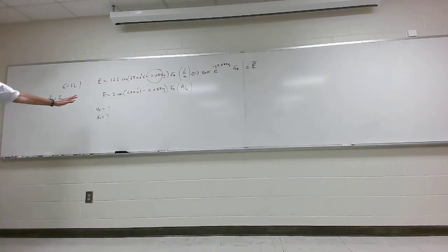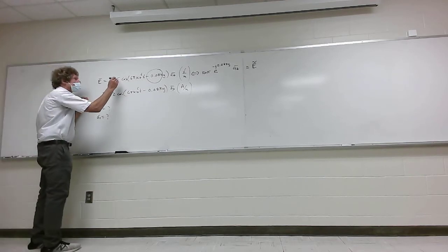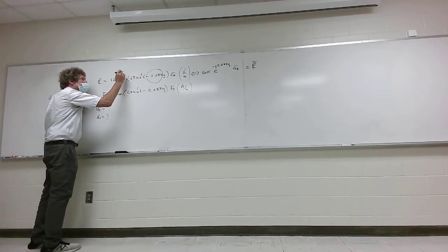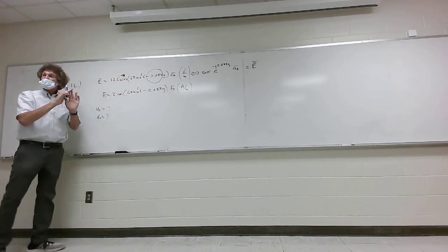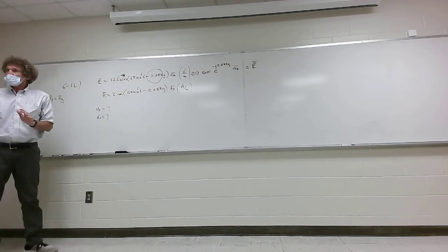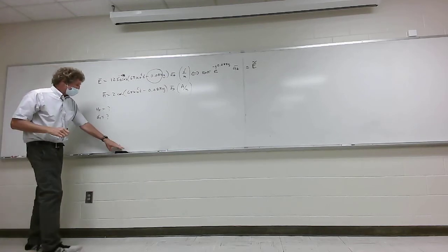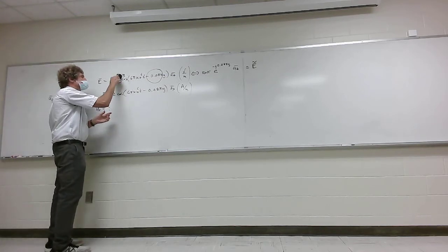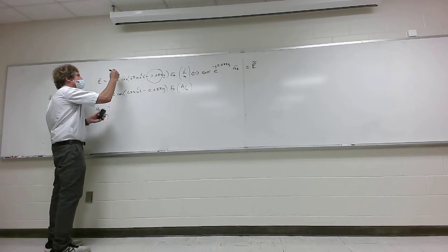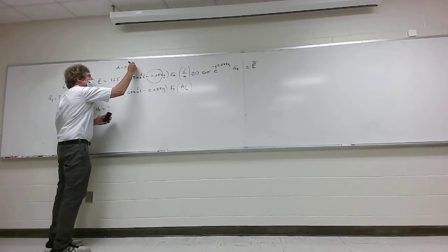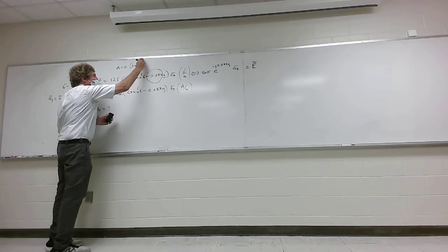All right, now he wants these things. You correctly identified the direction of propagation as positive AY. Now the next thing we need to do is figure out how to get these values. You all see there is no e to the minus alpha y, is there? There is no decay, so we know it's lossless. It's lossless because alpha is non-existent, it's 0. Since alpha is 0, we can say it's lossless, right?